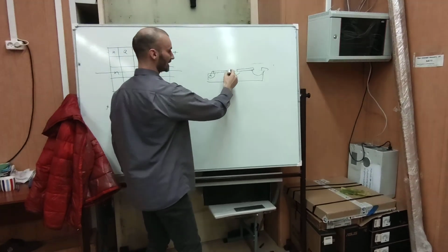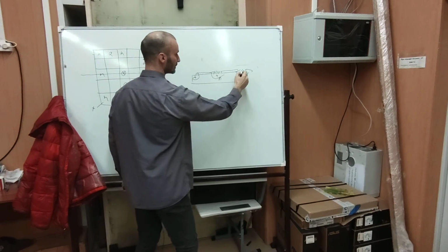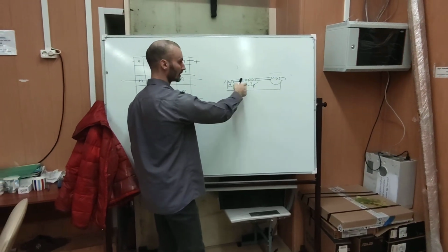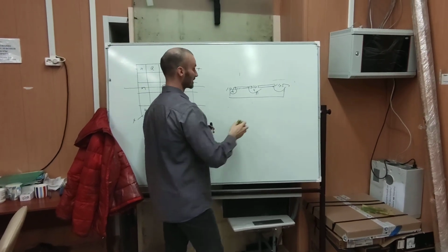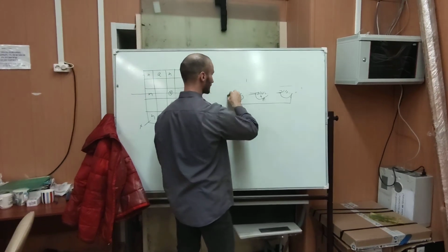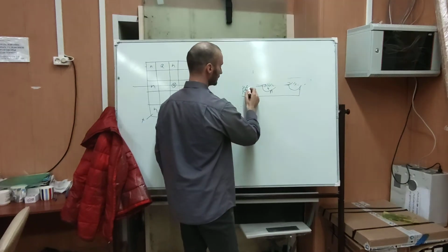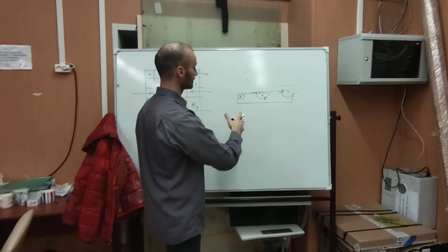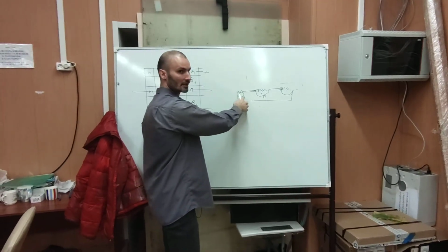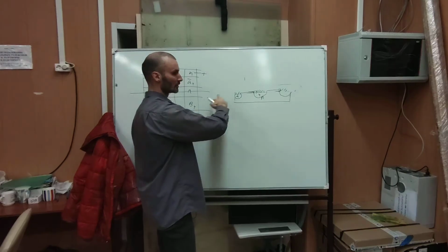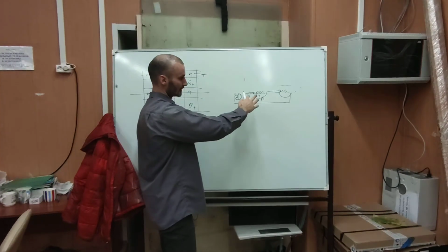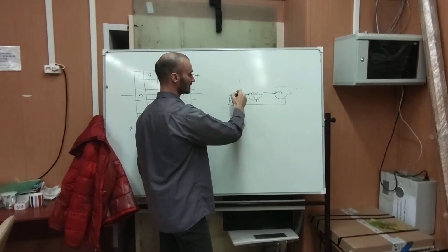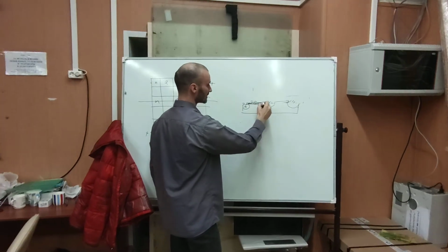Okay, and we will grow metal here. So we will have metal contacts here, here, and here. This way we will get connected to n-type semiconductor. Okay, next, as we have metal contacts here and here, we will grow insulator here. Same step with photoresist, but in that case we will heat up the semiconductor and apply some water vapor within some reasonable amount of time, and we will grow silicon oxide here. So here and here we'll grow silicon oxide, thin layer.